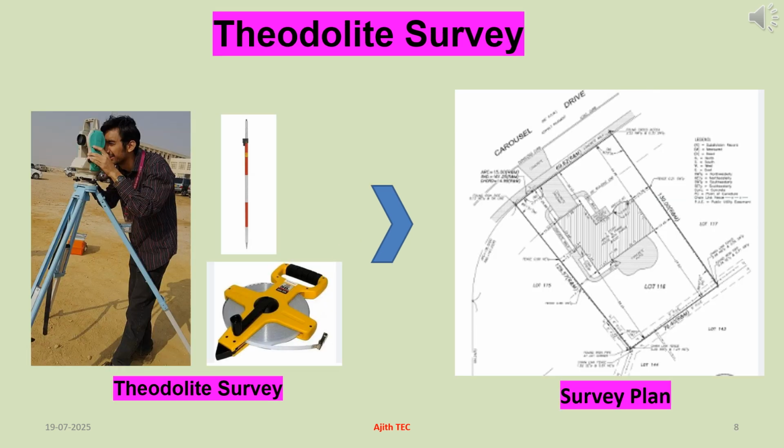This slide shows how to perform theodolite surveying with the help of chain or tape. It is important to run the outer boundary traverse according to the selected area for surveying. Then detail traverses should be run to collect required detail points as per requirement of survey. Finally, prepare the required survey plan according to collected data of ground features as well as user requirement.